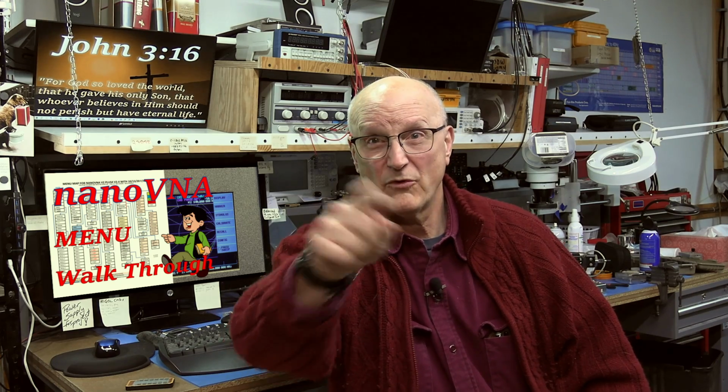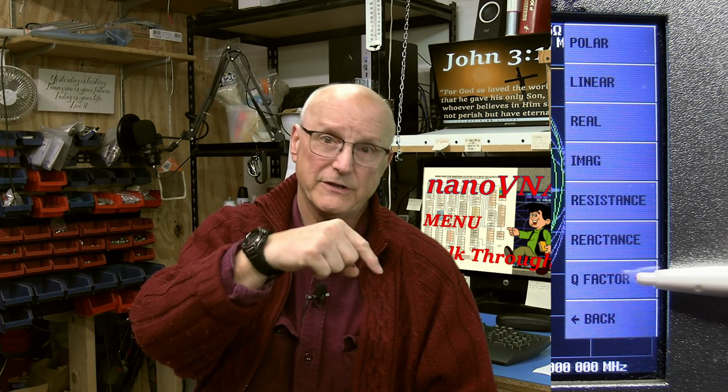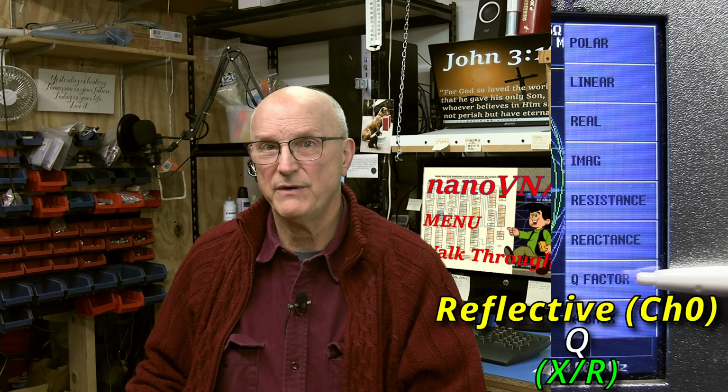But there's one more entry to go. If you're not familiar with what Q factor is, I have a nice video that will explain this in detail. There's a link up in the corner and down in the description to this video. It was amazing to me. The two manuals that I have for the nanoVNA do not even mention this option. So very quickly, there are two ways of calculating Q factor. In reflective mode, the Q factor of the device under test, as seen by channel 0, is the reactive part of its impedance divided by the resistive portion of its impedance.